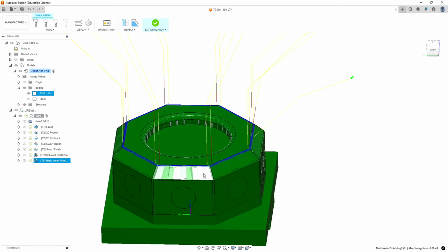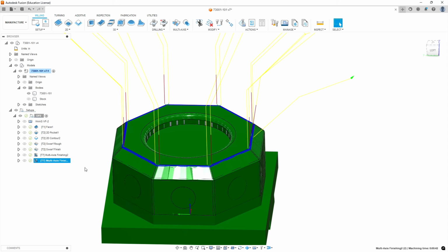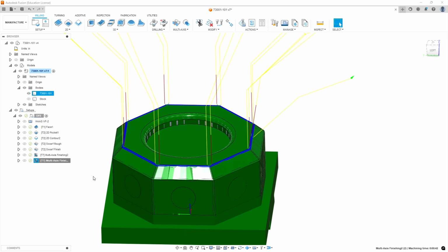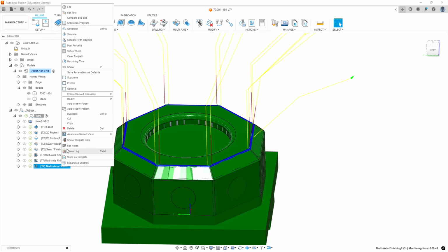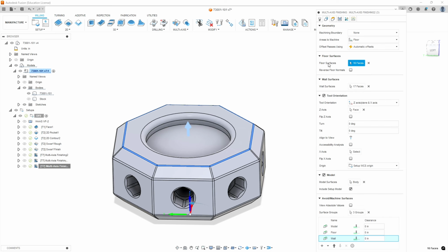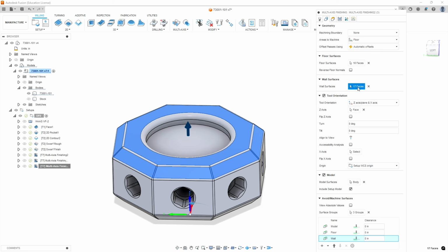Okay, now what we're going to do is copy that routine and do the fillets on the lower half of the chamfer with the same cutter. All right, so we're going to use the same feeds and speeds, and we're going to go to the next tab. We just have to select different items.